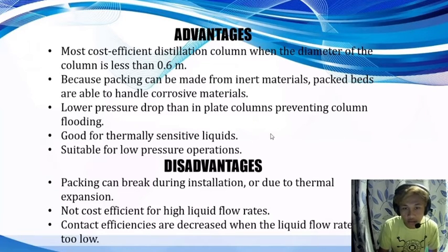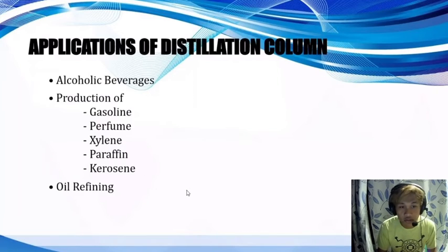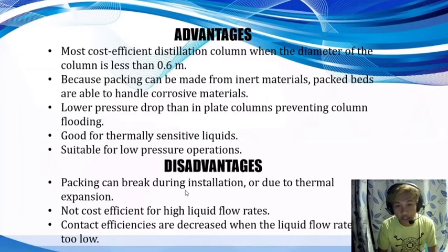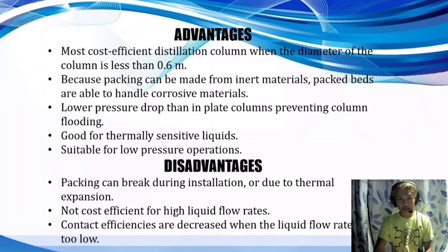So these are the disadvantages of a packed bed column. Packing can break during installation or due to thermal expansion. It is not cost efficient for high liquid flow rates. And the third one is that contact efficiencies are decreased when the liquid flow rate is too low.